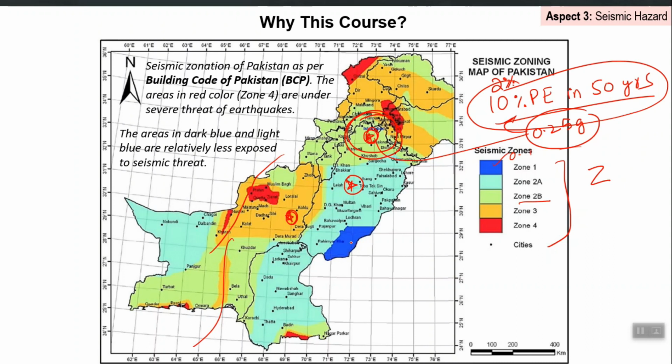So one of the outputs from the PSHA process is a hazard curve for each site, containing probability of exceedance on the y-axis and the PGA number on the x-axis, right. So at each dot on this map, I have a curve which will look like this. As you reduce the probability of exceedance, the PGA for the same site will increase.